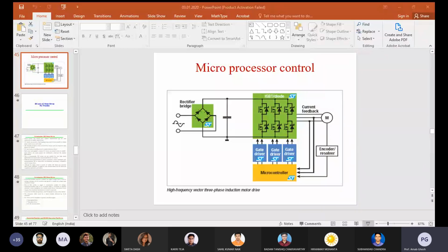So here you can see the AC supply, then you are doing the rectification. It is a control rectifier. Why control rectifier? If you change the firing pulse, the armature voltage VA can be changed. Increasing the firing pulse angle means the on time of the full control rectifier will be less, so definitely the voltage VA will be less. So the motor speed will be less.